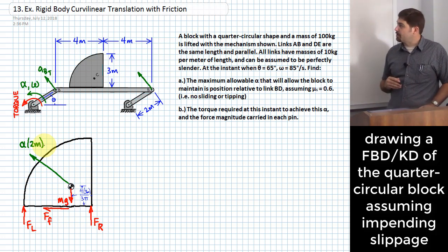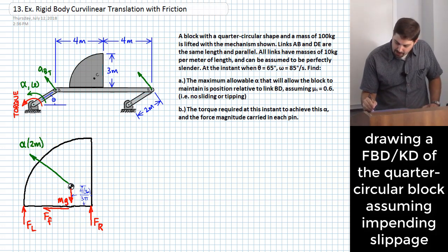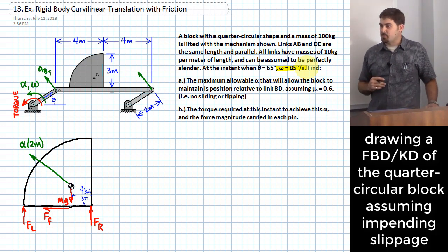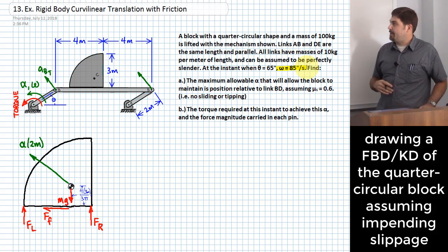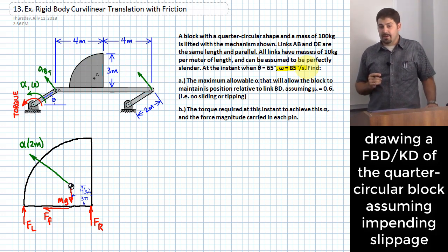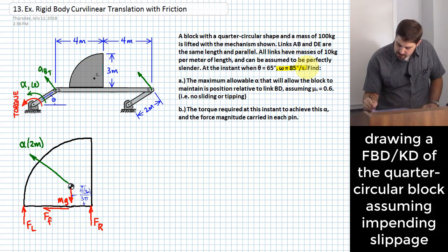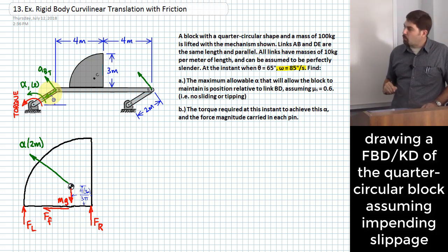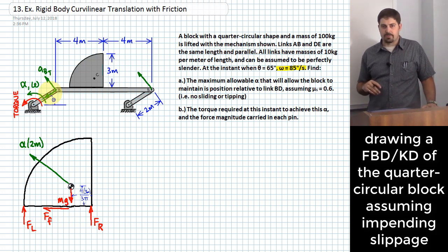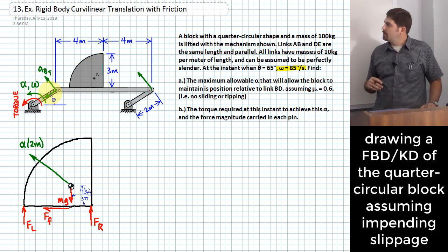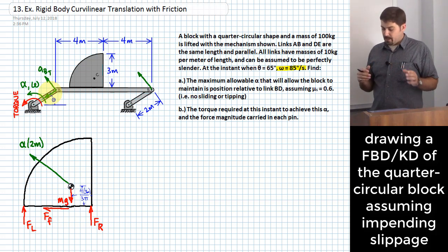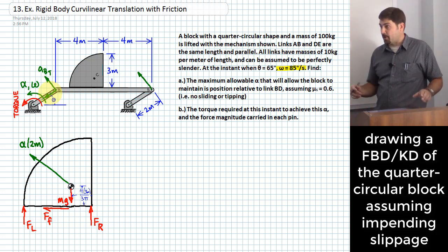Yeah, I have a normal acceleration because I have a non-zero angular velocity of link AB as well, right? I'm told there that I have an angular velocity of 85 degrees per second. That means that point B accelerates toward point A like this, according to what equation, or what kind of expression? Yeah, it's centripetal, right? Which means that you can take that angular velocity and square it and then multiply it by r.